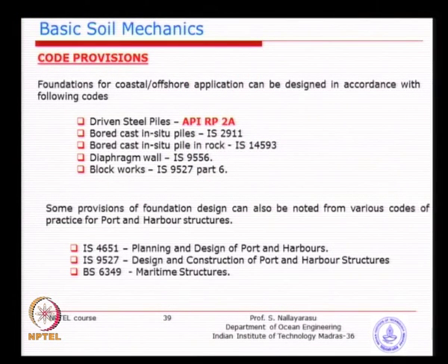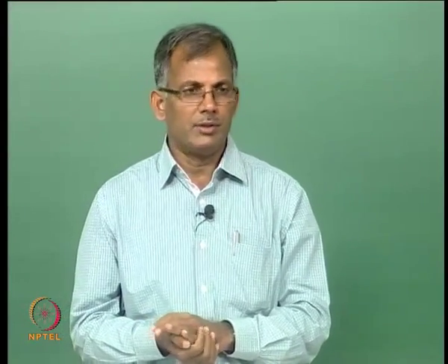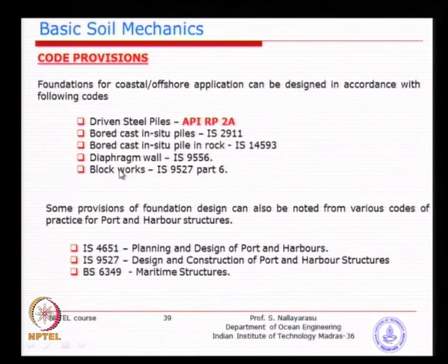And then the block work, I think I have shown you some picture of block work, simply pre-cast concrete blocks stacked with proper shear keys, so that they just don't slide. But basically the calculation here is the bearing capacity. When you stack very high blocks of say 10 meter, 20 meter, the total weight is acting on the seabed or the bearing layer. So, you need to look at the bearing capacity underwater.